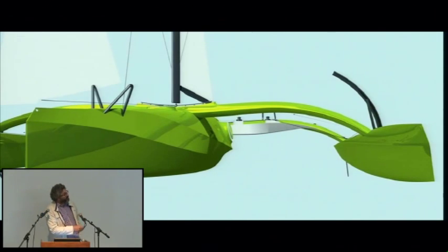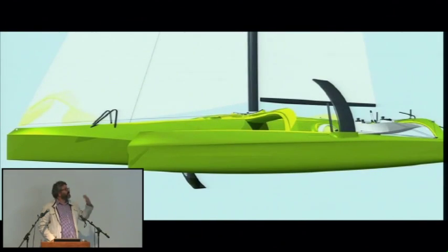So like this strake is something most boats like this will have to shed the water off. But a concave surface like this, most won't have. But it turns out when the boat buries in the water and you want it to pop back up, this surface turned out to be a better surface than a flat surface. Or the kind of axe shape, which was purely to look like a Japanese sword, turned out to be very successful in punching through waves. So there were all kinds of styling things which were not the consequence of optimization, which turned out to have consequences.